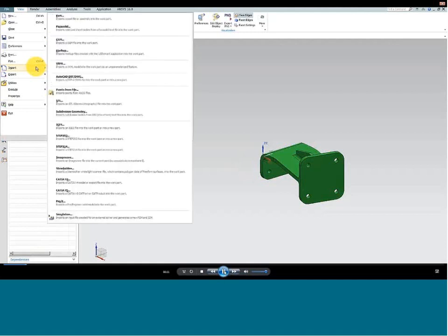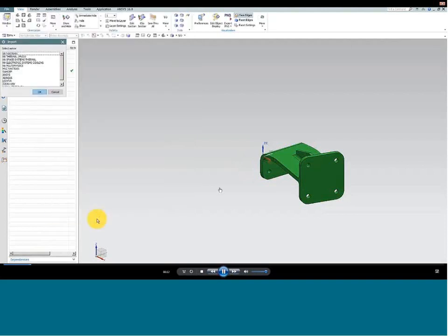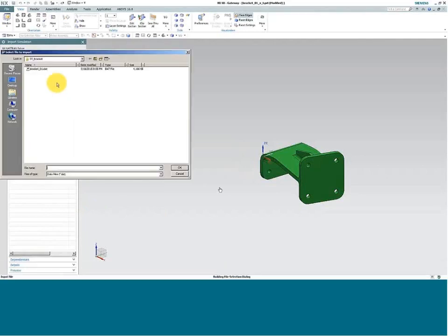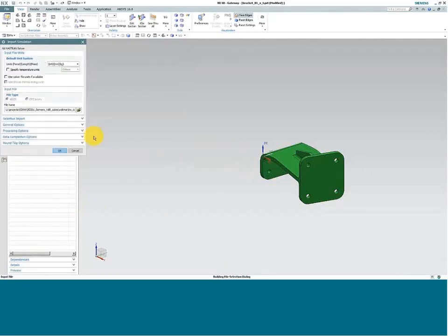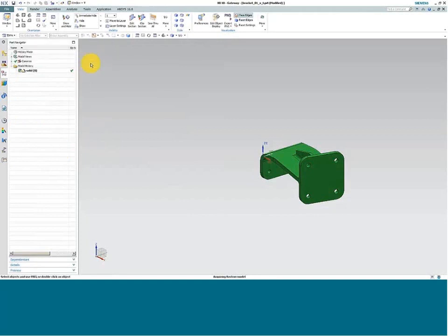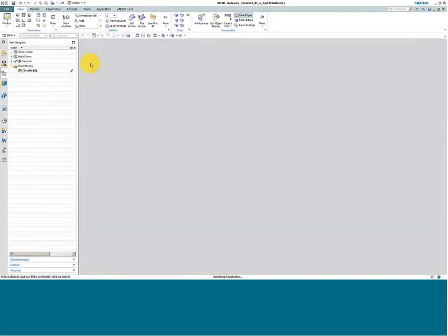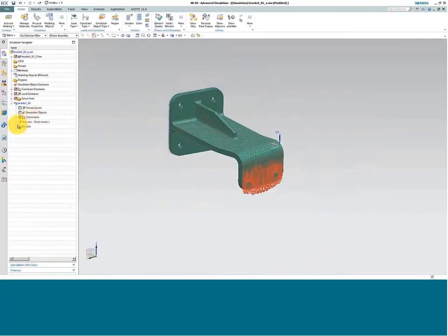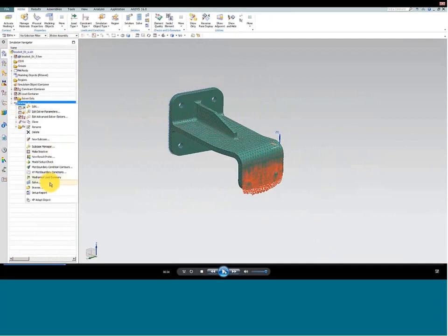But whatever the case is, suppose we do have this representative CAD geometry on which we would like to associate nodes and elements. So the next thing I'll do is import an NX Nastran model that represents this bracket. I'll just accept these default settings and bring it into NX. Even though this is all within the same NX window, I really have two files open here. I've got a simulation file or FEM file with these nodes and elements, and I've got the part file containing that CAD geometry, but the two haven't been tied together. They have not been associated yet.